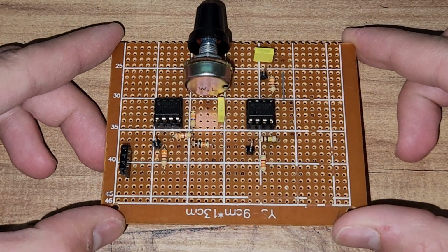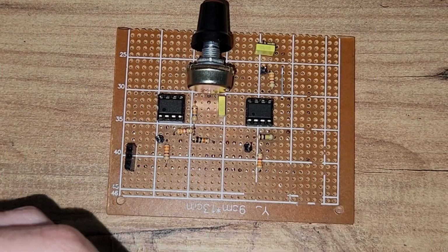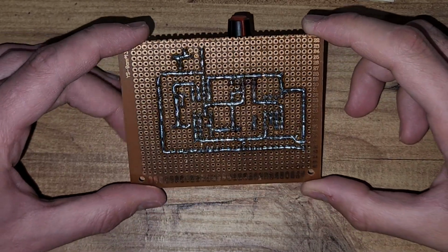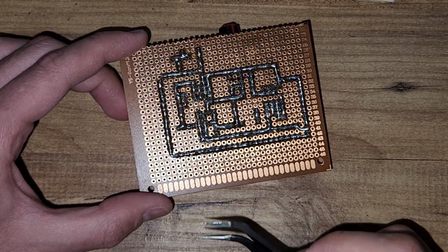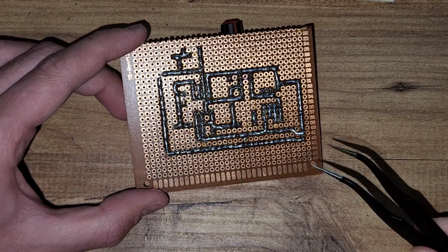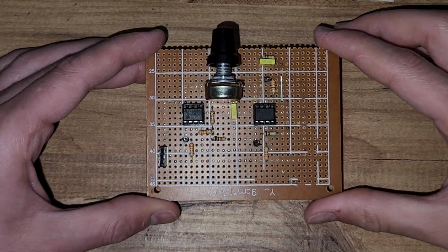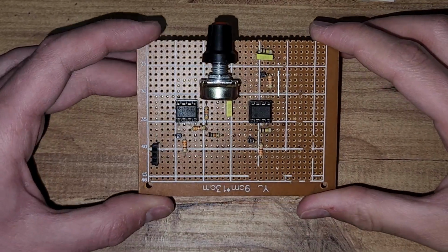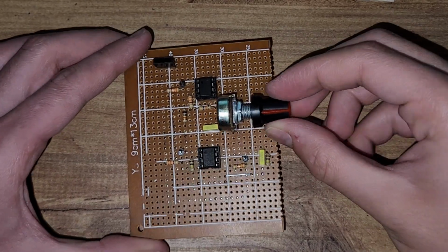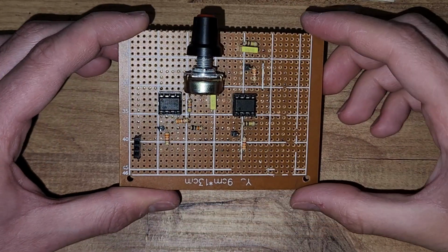If you want to make a more permanent version of your function generator, you can solder the components onto a printed circuit board (PCB). This will make your circuit more reliable and less prone to loose connections. To do this, you will need to transfer your breadboard design onto the PCB. Next, you will need to solder the components into the PCB, starting by placing the components onto the board and using a soldering iron to attach them to the board. Be careful not to overheat the components and to ensure that the solder connections are strong and secure.